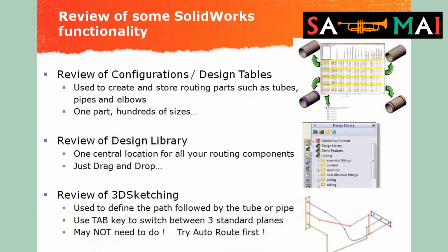This is what I usually go over when we do it as a hands-on, because these are the things you're going to need to know to be able to do routing successfully. But this is also important information for you guys. So just to know, what you need to know to be able to successfully do routing is you need to understand configurations and design tables, because that's how the pipes and tubes and elbows and everything work.